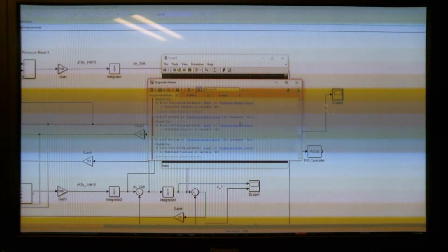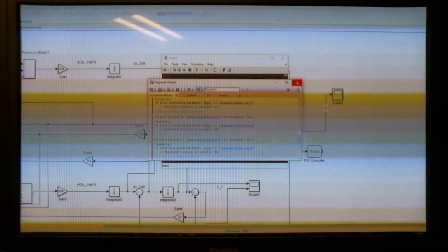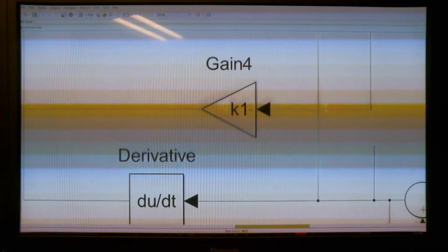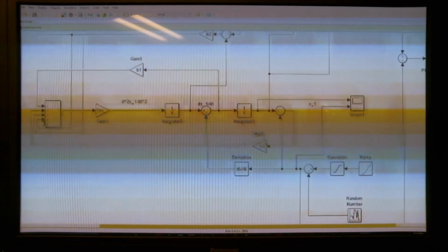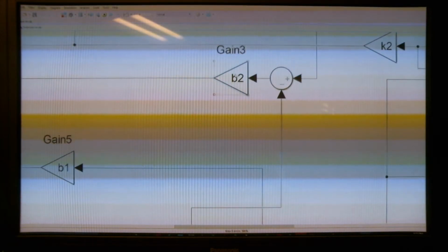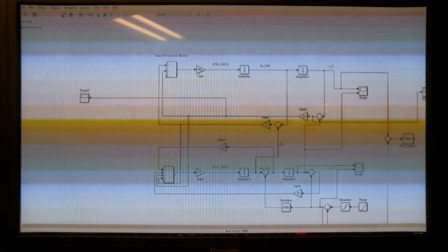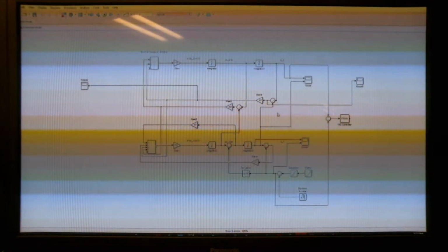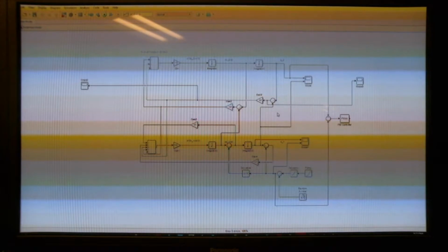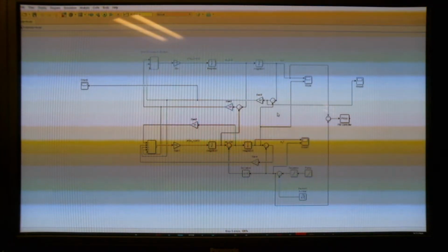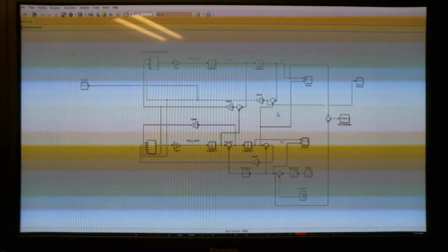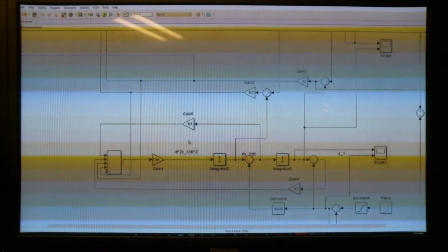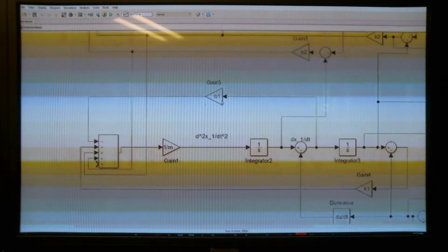So you get a bunch of errors. What I've done is I've defined parameters for spring rates, damping coefficients, etc. You can do that. You can take models from other stuff, take data that you've already collected from, let's say, experimentation or data collection otherwise, and use that in your Simulink models.